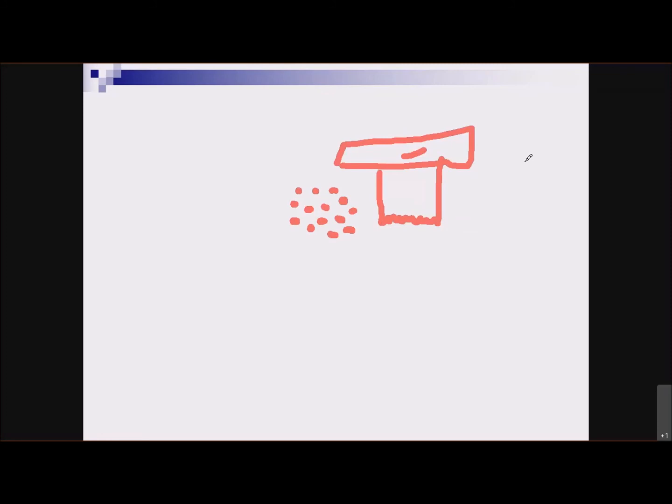That amount of current is then translated by the electronics in this sensor and sent out to the PCM as either a variable voltage or a variable frequency. So the actual operation of the sensor, the hot wire, and keeping that wire hot is pretty much the same whether it's a frequency type sensor or a varying voltage type sensor.